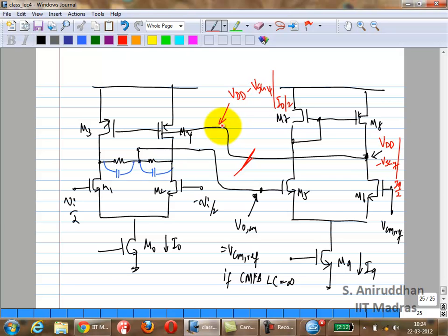It's a random effect. Ideally, yeah, you can use larger transistors and so on, larger areas, but there's not much you can do about those random effects. That's a fact you have to live with. You can at least get rid of the systematic offset. That's what we have been studying so far, right? Number one, first thing you do is eliminate systematic offset, systematic mismatches. Next thing, find techniques to minimize random mismatches. That is the best you can do with any circuit, right?